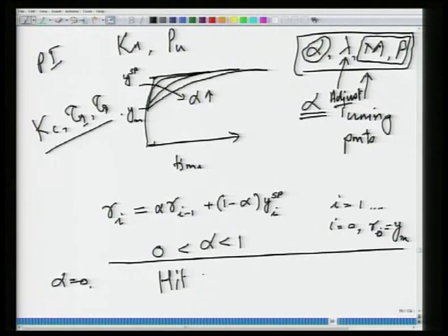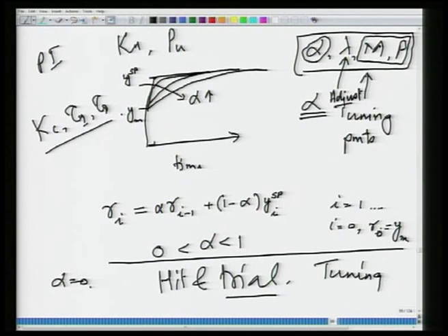You keep on adjusting lambda until you get the kind of control performance that you want. Okay. So, tuning is essentially hit and trial, and that is one of the major disadvantages of essentially all MPC techniques, all model based control techniques. Okay. And because the tuning is not trivial, you do not have a standard procedure to just blindly apply. It requires effort, and engineers, somebody remarked, are by definition lazy people.